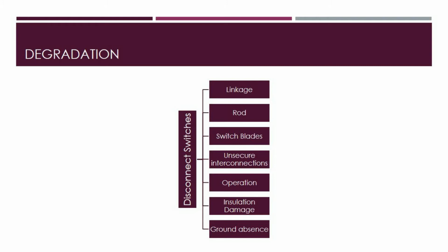Disconnect switch enclosures that are installed on the pad or vault are susceptible to corrosion from road salt. Other major faults that might emerge with age include non-functioning padlocks and damaged interface barriers.